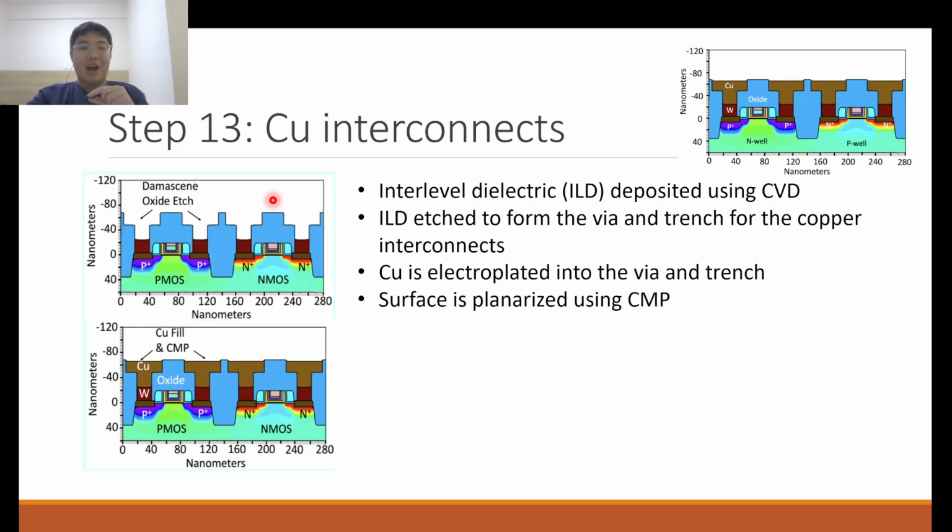However, for copper, every etch chemistry results in non-volatile byproducts that will fall back on your wafer and contaminate it. So copper is not able to be etched in the same way as aluminum. And that's why CMP technology became very important when copper was used, because CMP is the only way to remove copper from the surface, by physically and chemically polishing and grinding it away.